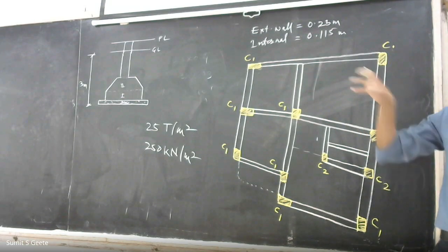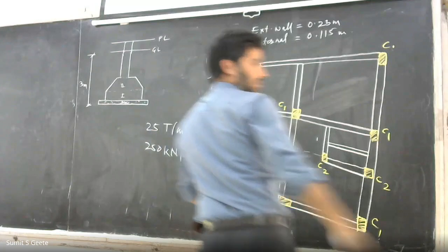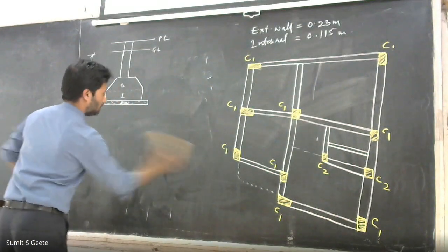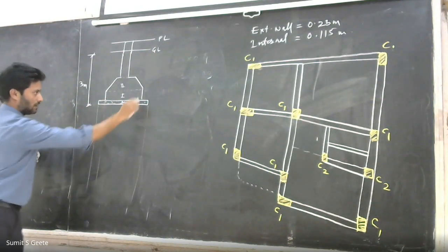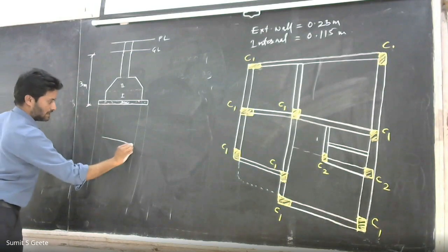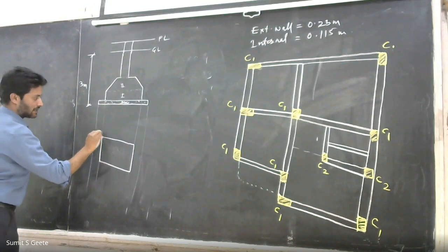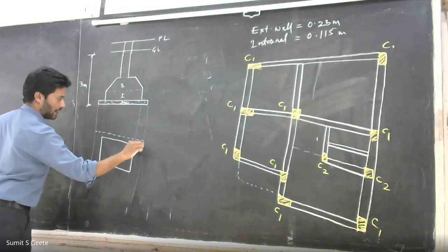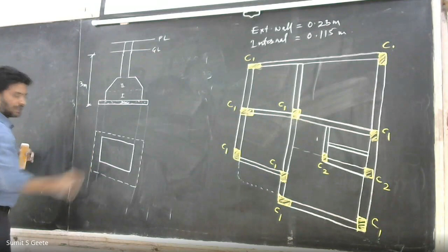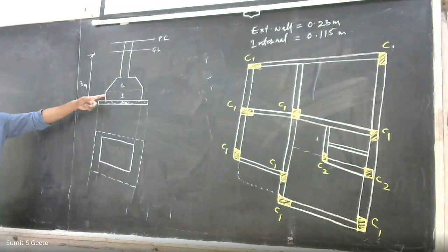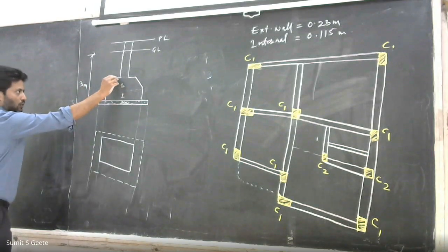So what I will do, I will first draw a plan of this. ये तो क्रॉस सेक्शन हो गया। अब इसका प्लान कैसे रहेगा? This is the footing line. This is excavation line. As in case of BDD, excavation line is always drafted in dotted line. So this is excavation line. This is footing line, and over this two parameters, it is again necessary to locate